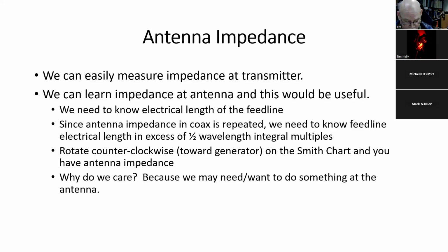And the Smith chart, the tool we use to measure impedance at the input to the feed line, may help us assess what's the impedance at the antenna and then make a decision as to whether or not we want to do anything at the antenna or live with what we've got.